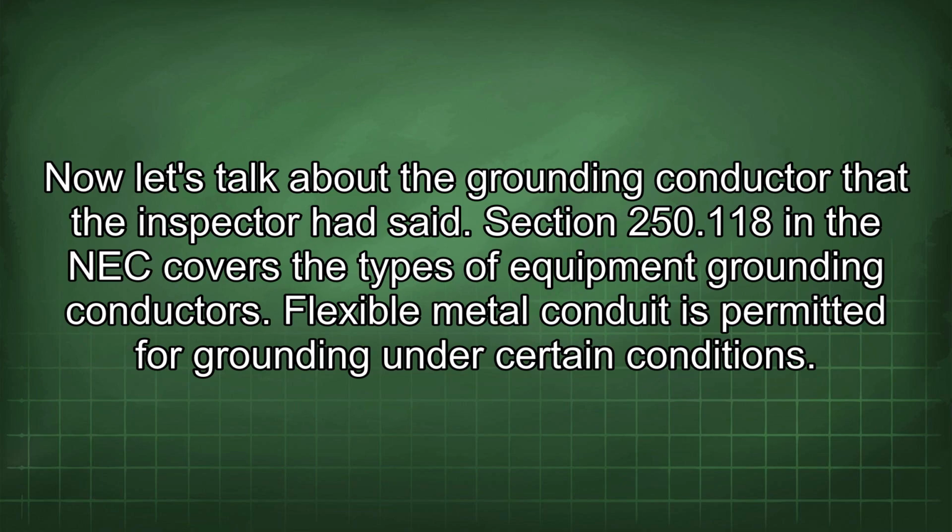Now let's talk about the grounding conductor that the inspector had said. Section 250.118 in the NEC covers the types of equipment grounding conductors. Flexible metal conduit is permitted for grounding under certain conditions.